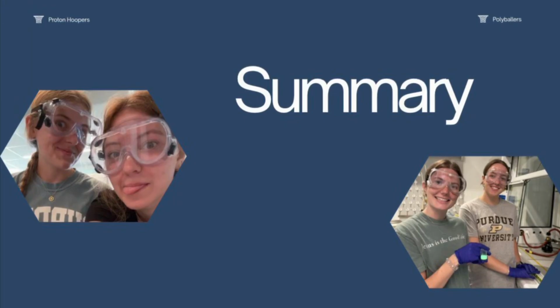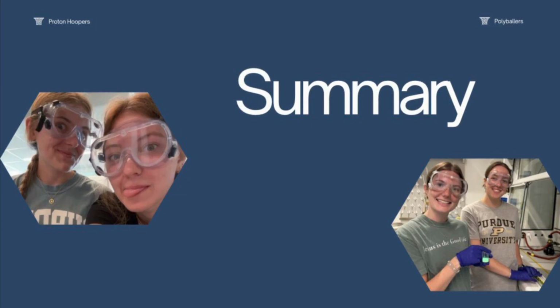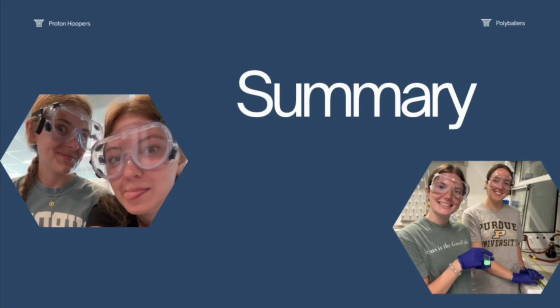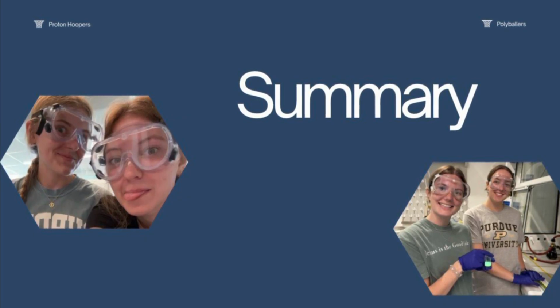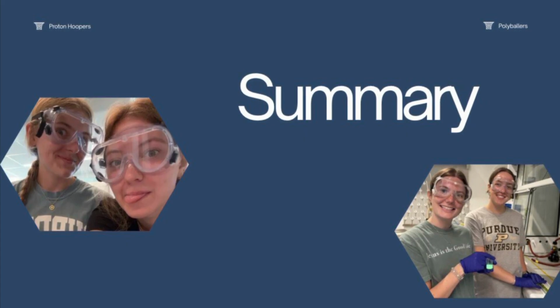Now that we just watched that exciting ending to the biggest game of the semester, let's do a little recap to summarize all of the information. Today, we have taken a deeper look at polymers and their real-life applications, such as fabric adhesive materials. We have looked at what a polymer is, the 3 different kinds of polymerization, and 2 major classes of synthetic polymers. We went in depth on the 2 different kinds of synthetic polymers, chain growth and step growth, and the 3 different types of polymerization, free radical, anionic, and cationic. We then learned about the 2 different kinds of heat transfer vinyls, polyurethane and polyvinyl chloride.